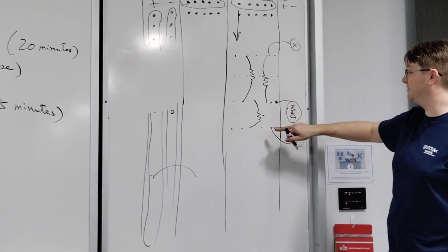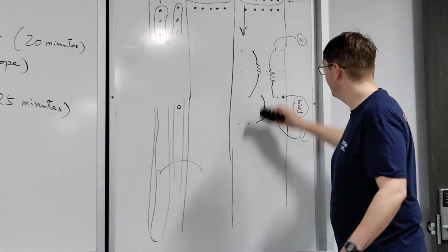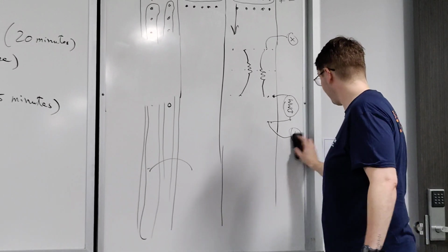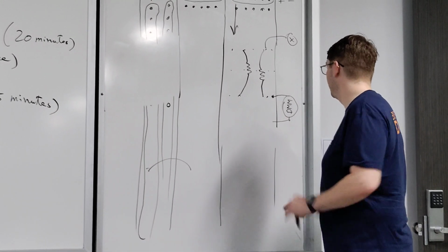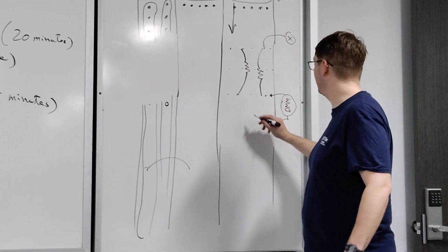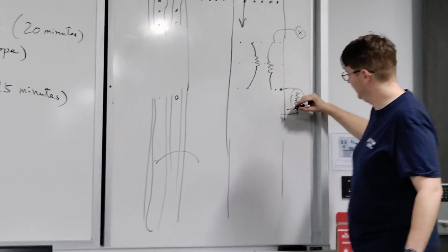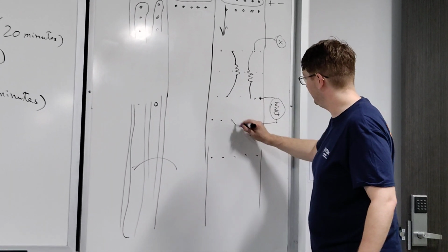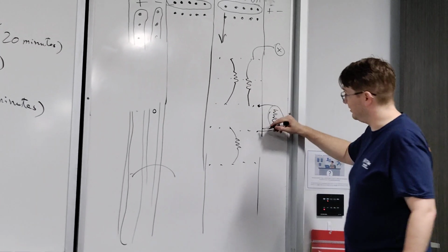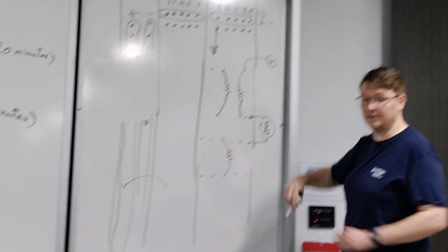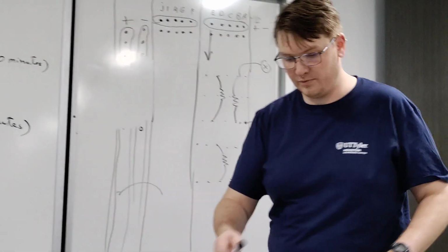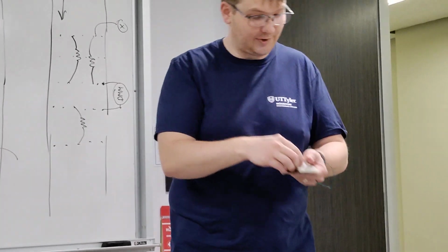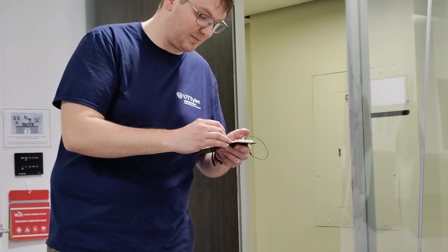If I want to measure the current through this resistor, I need to break the circuit and insert the multimeter into the circuit so that all that current can go through. So in this case, we're going to have these parallel, then I'm going to have the multimeter just in another line, and then I'm going to add that resistor back in. And that's going to tell me all the current that has to flow through this before it gets to the end of the circuit.